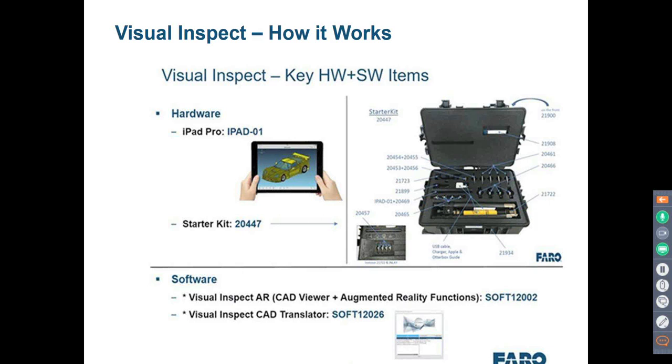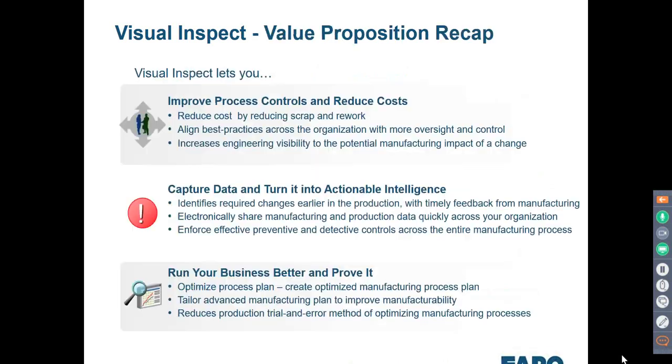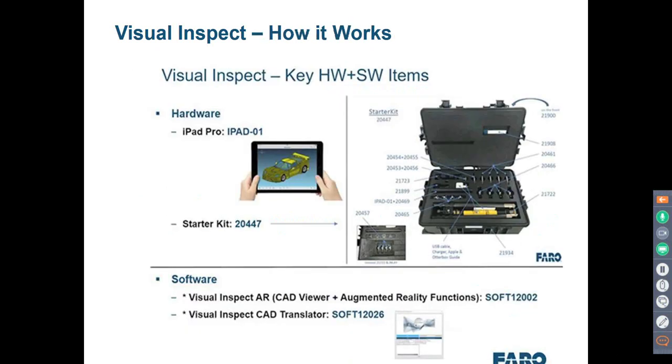You can overlay or reference this picture by giving detailed pixel points. So you say this pixel point belongs to this CAD point, or if you have markers in your picture, you are able to use the markers there. But either way you do it, the picture and the situation of your augmentation is stored inside the model tree. So when you give the model away or send it to your colleague around the world, he can just examine the same situation wherever he is.